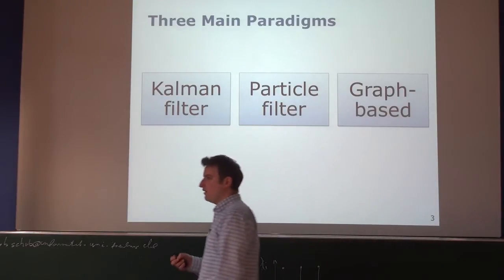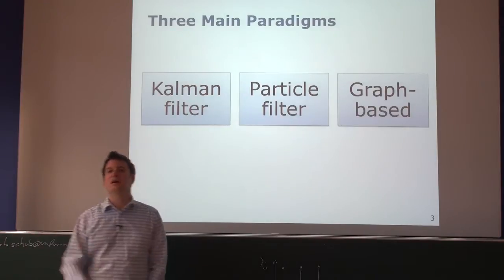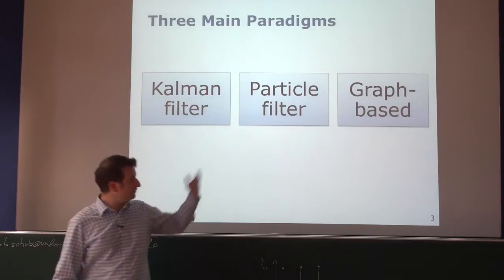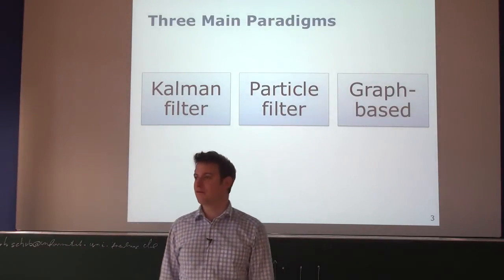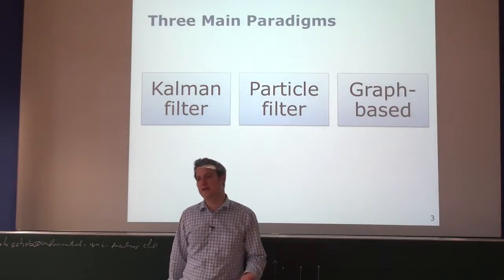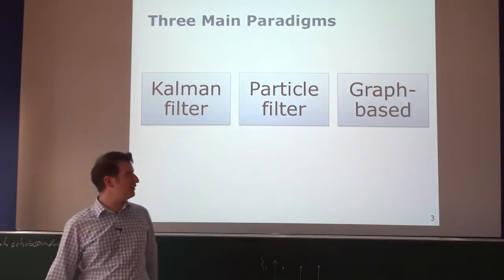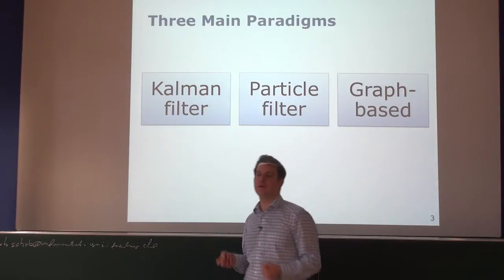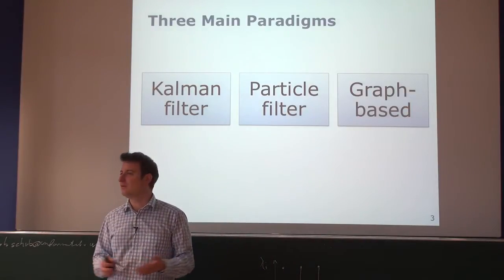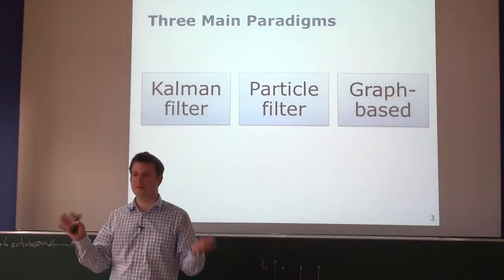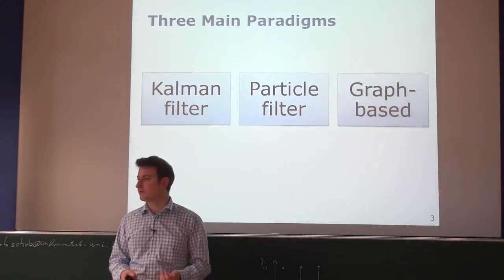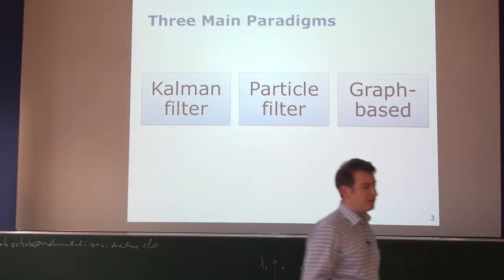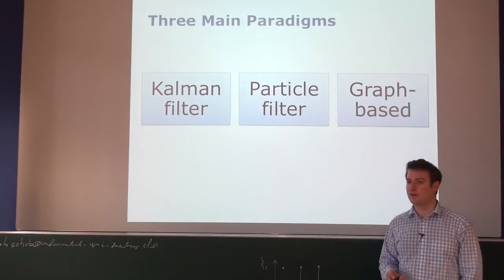And finally, last but definitely not least, the graph-based approaches, which we presented in the end, which are motivated by reducing the sum of squared errors, which can be shown to be equivalent to finding the mode of a Gaussian distribution. And there are some nice advantages of the graph-based framework in terms of the flexibility it gives you in terms of linearization or relinearization, so that the graph-based approaches are the most popular ones, at least among the more modern systems proposed after 2006, perhaps. Before that, the Kalman filter was the dominant system, but the graph-based approach is very, very frequently used in the context of SLAM.